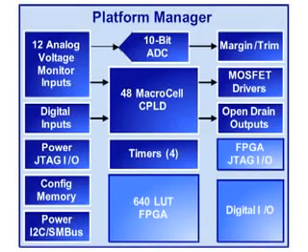Platform Manager includes analog I/O pins to monitor board voltages and currents, a CPLD for control and timing of board power management functions, and an FPGA for extended digital board management functions. As an integrated solution, Platform Manager is low-cost, flexible, fast, and accurate.